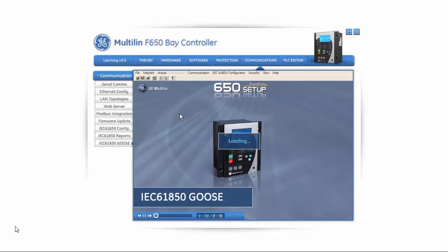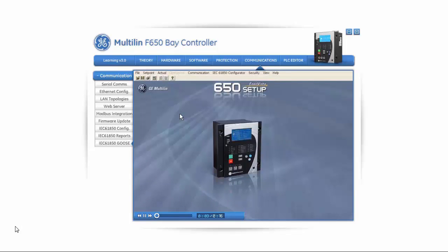The IEC 61850 GOOSE allows sending and receiving digital and analog information. The digital information can be the status of flex operands, contact inputs, protection elements, or any other internal status inside the relay that needs to be communicated to another IED or system. The analog information can be currents, voltages, power, or any other analog value that the relay can measure.